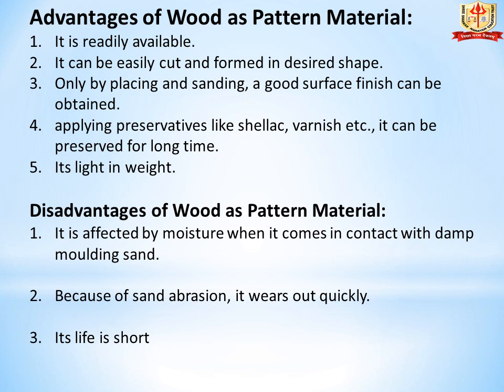Next point, disadvantages of wood as pattern material. First point, it is affected by moisture when it comes in contact with damp molding sand. Second point, because of sand abrasion, it wears out quickly. Point number 3, its life is short.